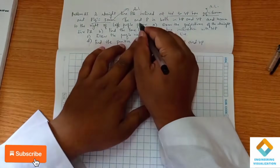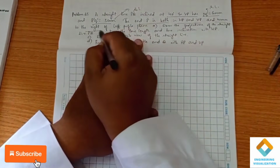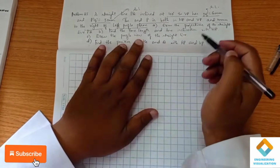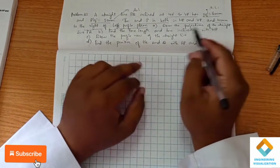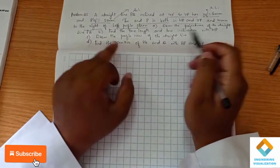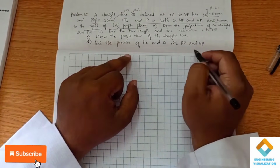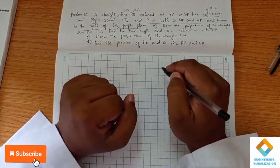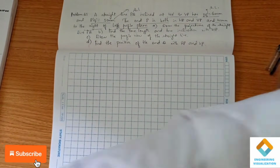End P is in both HP and VP, and 40 mm from the right or the left profile plane. Draw the projection of straight line PQ, find the true length and true inclination with HP. Draw the profile view of the straight line and find the position of the end Q with HP. In this problem, you have to find out the side view also.